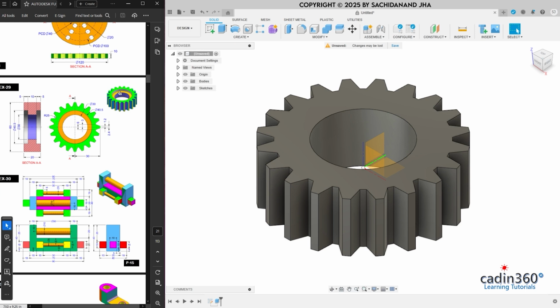So we have this slot on one side and it is on another side too. Okay, 40.5 in dia and depth is 5, so it is also on the opposite side. So first we will create it on this side, and then we will use this mirror plane which is the base plane of this model, and it will create a similar profile on the other side. So that's why we use the symmetric extrusion method, keeping in mind the future problems.